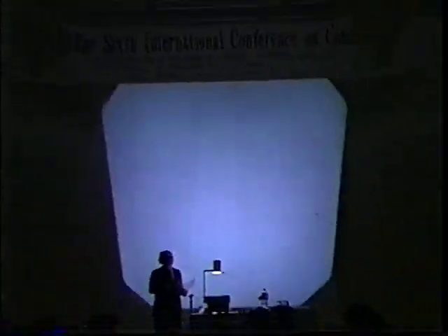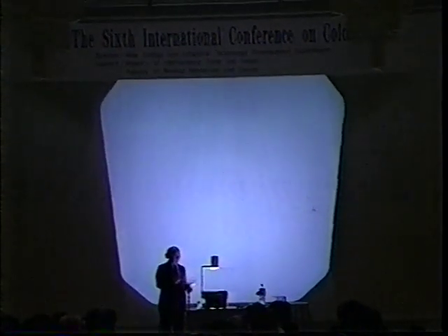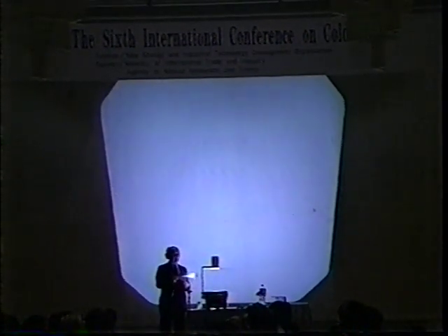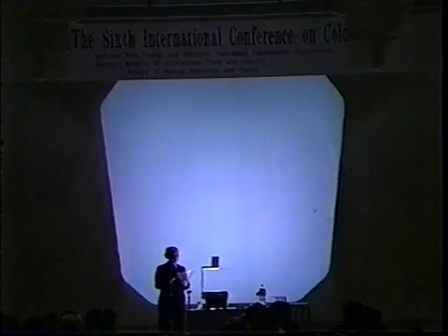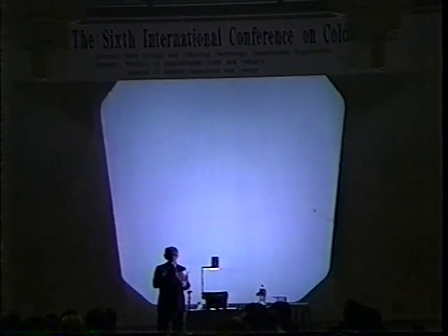Now, at boiling, and when you get very close to boiling temperature, first of all, you have to realize that in that case, you never reach boiling. And the reason why we never reach boiling is that the gas stream contains both water and hydrogen or oxygen. So the bubbles are not pure water bubbles.